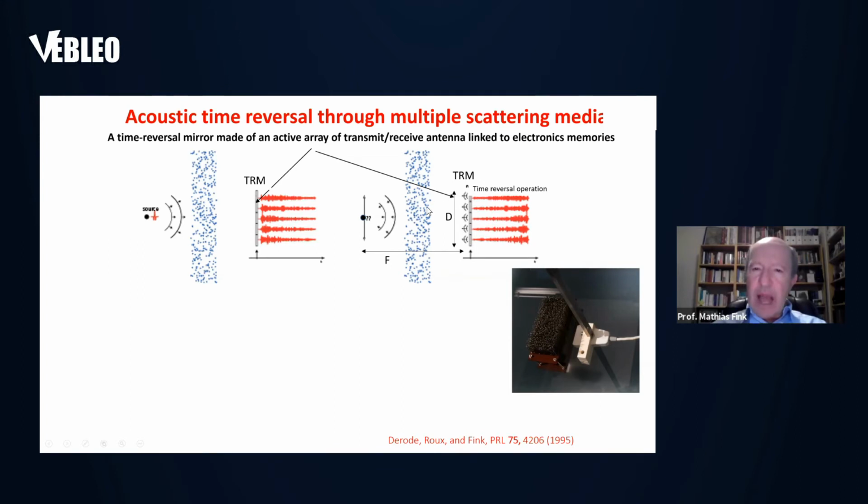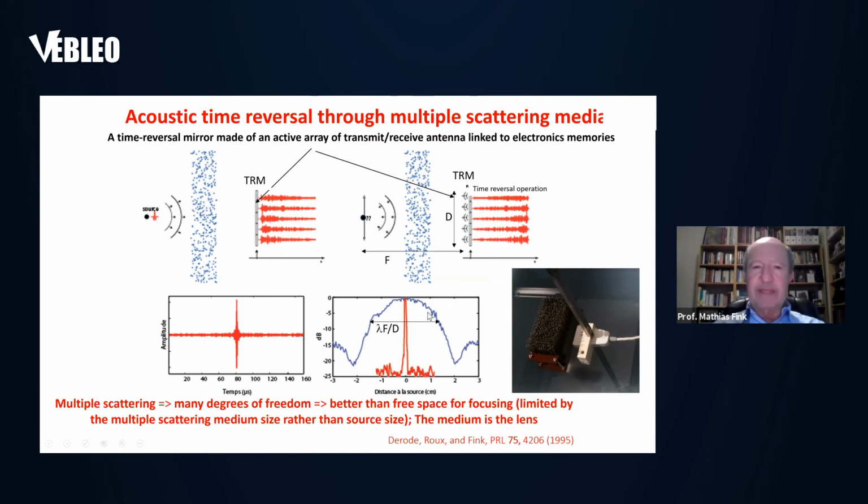And when you look at how the time reversal process goes, you can look at the size of the focal spot you have here, and at the signal that you receive at the initial point. You see that when you send all this long signal, in our experiment, when it comes back here, it is compressed. You have completely canceled all multipath. Second, when you look at the size of the focal spot, by moving your antenna here, you see that the size is very thin.